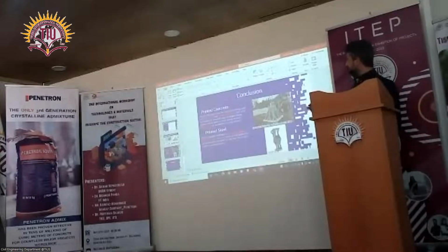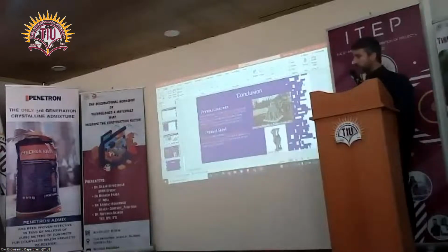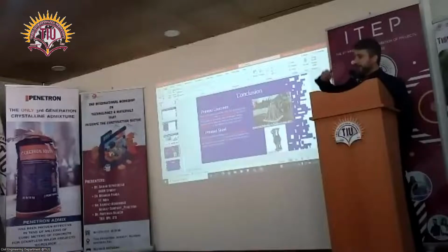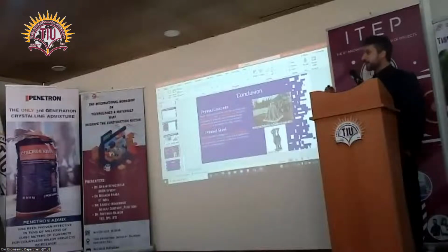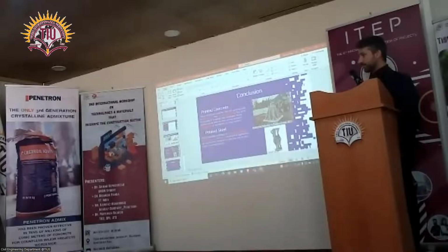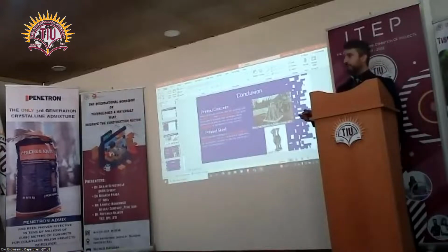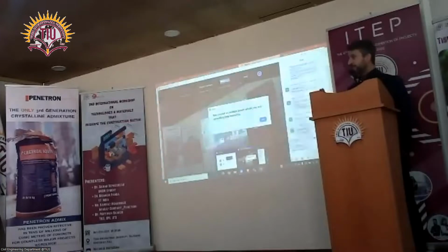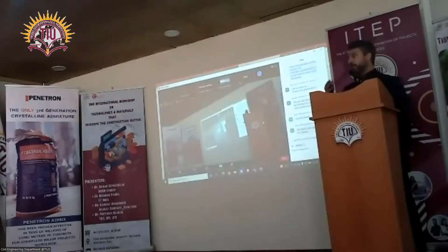Actually, this pole made by Hyperion Robotics also contains steel. Some of the steel can be added by bolt and nut, like a screwed bolt inside, and you can replace the rebar inside any kind of element for structural purposes. But in terms of durability, we need more time to see if we have cracks, especially cracks from shrinkage or creep in our structural element. We need about 3-4 years to see what is going on with this kind of foundation.